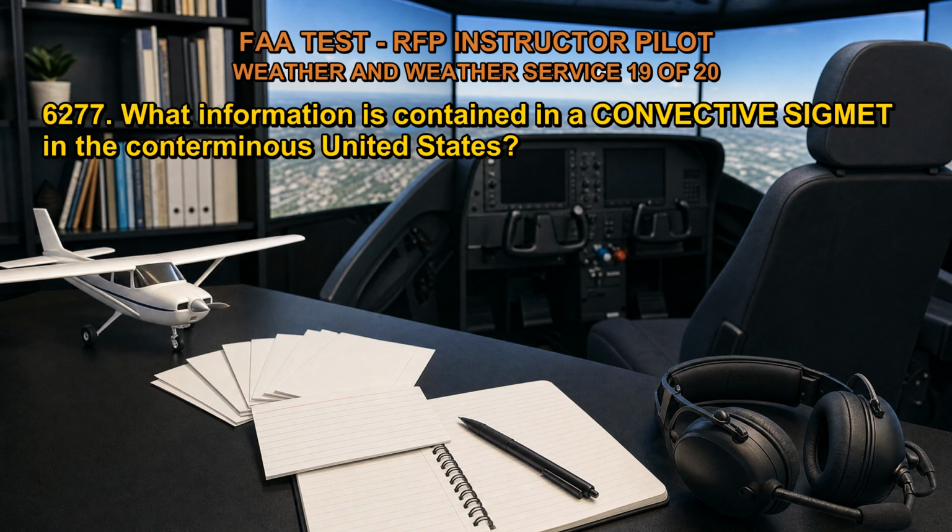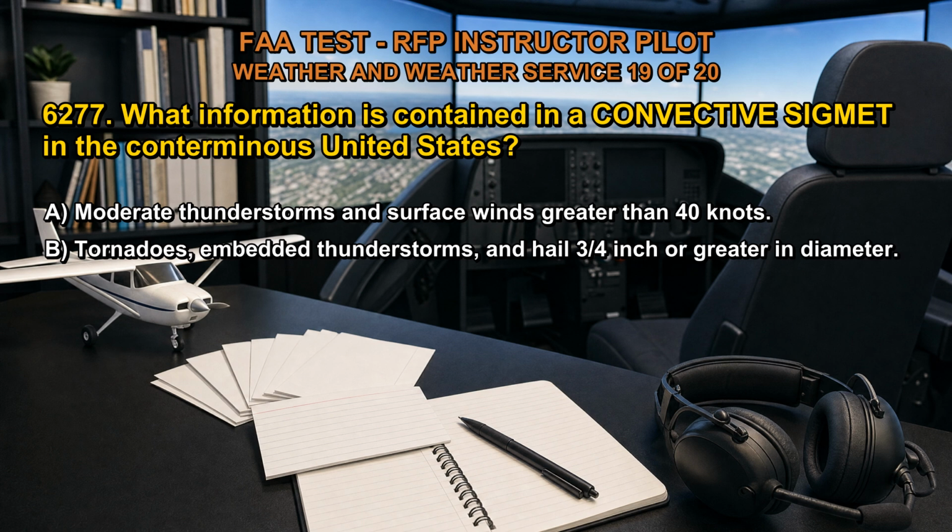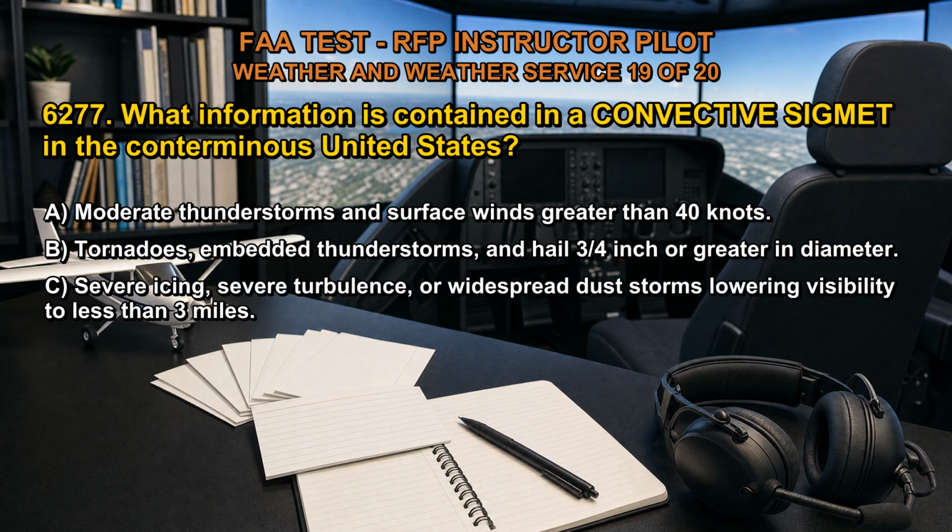6277. What information is contained in a convective SIGMET in the conterminous United States? A. Moderate thunderstorms and surface winds greater than 40 knots. B. Tornadoes, embedded thunderstorms, and hail 3/4 inch or greater in diameter. C. Severe icing, severe turbulence, or widespread dust storms lowering visibility to less than 3 miles.